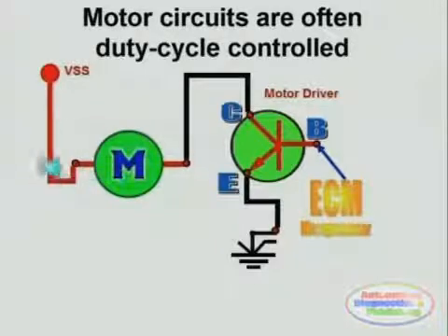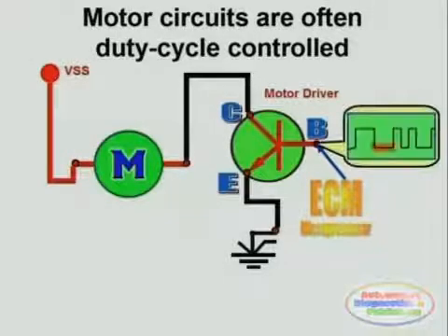And always remember that duty cycle control circuitry has to be performed by a transistor. Relays cannot be used to duty cycle control a component, since the switch rate of a mechanical relay is not fast enough for this duty cycle signal to go into effect. The effective control of the component connected to this duty cycle control circuit changes depending on the pulse of the duty cycle.